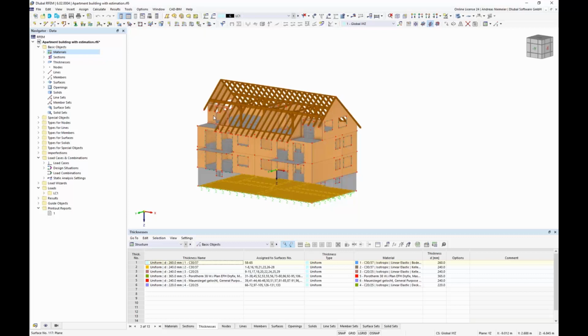If you want to use it more advanced, you can use it, for example, to decide if you should use a frame with bending moment resistant frame joints, or if you should create this frame by cantilever columns, or as mentioned just before, you can use it for deciding if you should use timber or concrete or aluminum or whatever, according to different reasons, maybe according to CO2 emission reasons. So all these options you have, and this gives a lot of possibilities.